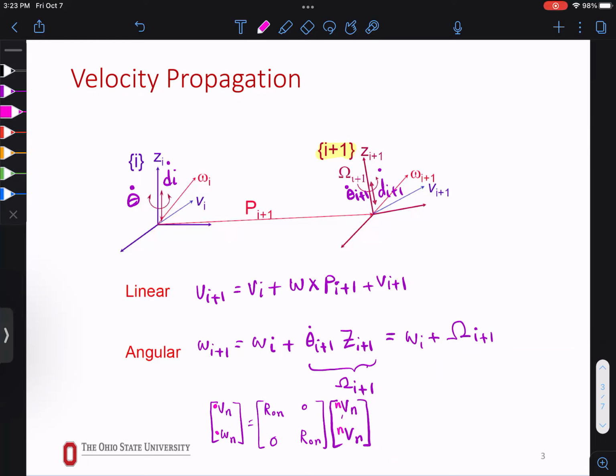When we talk about dynamics, what does velocity give us? Momentum, force, right? If you're braking an actuator, if there's too much torque on it, how do you calculate? Okay, I'm going to see how many joints and lengths are after this actuator, and I want to see what the torque is. And I check the torque that this motor can sustain. If it was more, it's going to break.